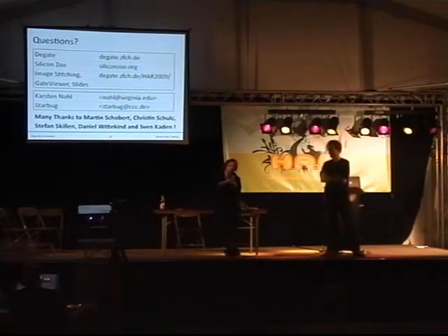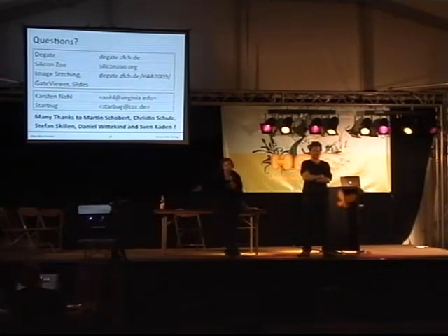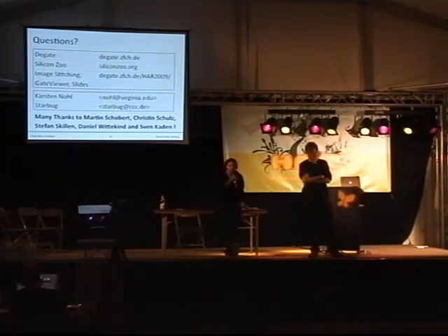If you're trying to flatten the chip so it's not tilted, but it is tilted, you polish half of the chip, make pictures, polish the other half, make pictures, and stitch it together. So if it's not totally untilted, it's not a problem. It's only a problem if it's an angle of 1 degree or so. Otherwise, it's not a problem to also reverse engineer up to 8-10 layers.